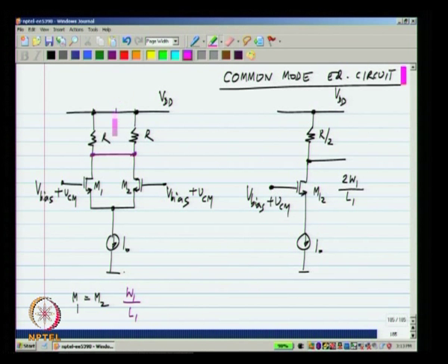Now, this came just from the symmetry between two halves of the circuit. All we said was we have a symmetrical circuit, we apply equal inputs to the two sides. So, that means that the voltages in each half will be the same, they can be connected together. So, if we have a symmetric circuit like this, we can fold it up, connect the corresponding nodes, and come up with a simpler circuit with which we can analyze.